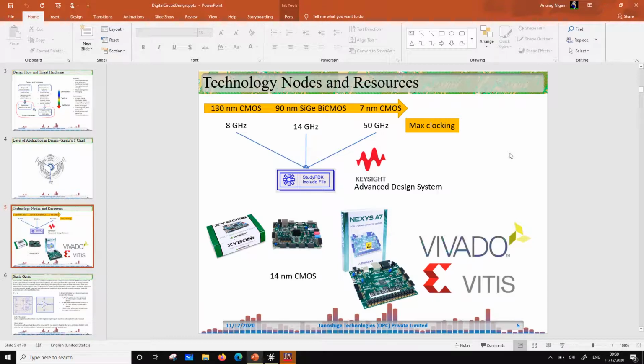So earlier you used to use what are called MOSFETs, and these MOSFETs are 3-terminal devices, which have got drain and source, and they have got a gate, right, which is a controlling element between drain and source. So this gate length is usually called the minimum feature length, the minimum gate length, by which we identify a certain CMOS technology. This gate length has been progressively reducing.